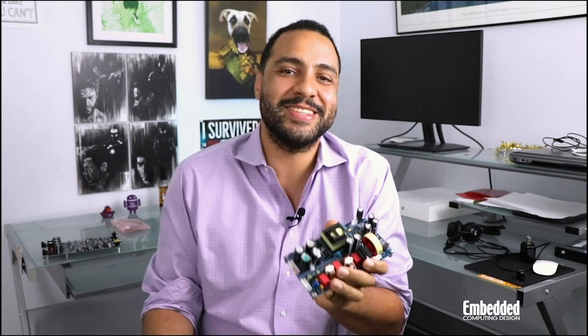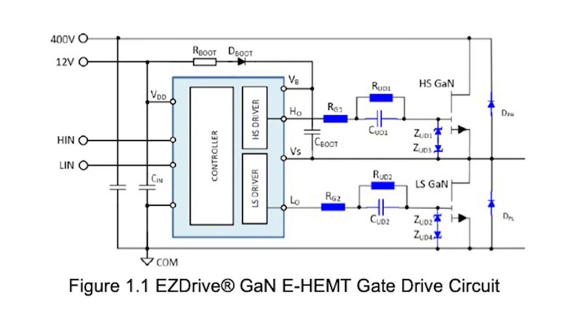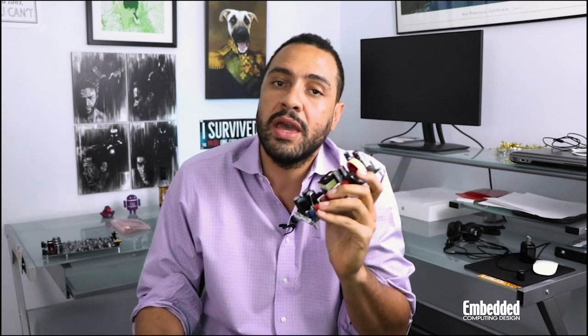Now, the other board, the GS EVB AUD SMPS 1-GS, is home to the 650 volt 22.5 amp GS66506T enhancement mode GaN-on-silicon power transistor. It's based on GaN Systems Easy Drive circuit, which can be adapted to any switching frequency, power level, or LLC or PFC controller to optimize system cost and ease of use. The GS66506T 650 volt eHEMTs have all the same features as the GS61008P device cousins and boast low total gate charge and output capacitance to provide low switching losses and high efficiency.